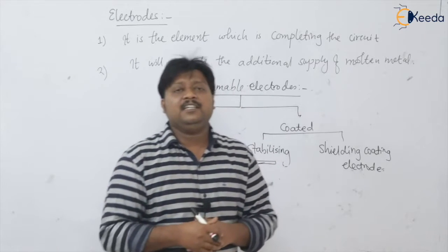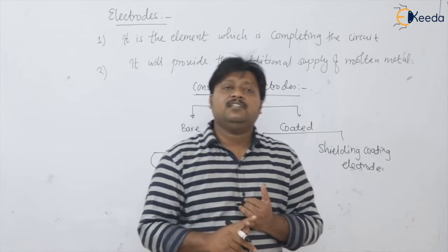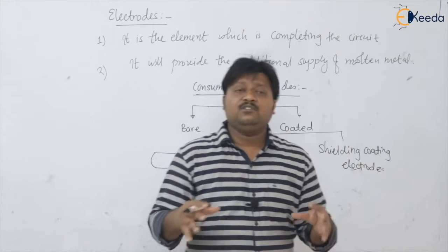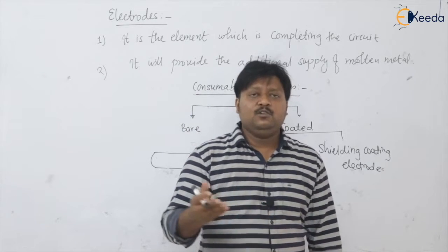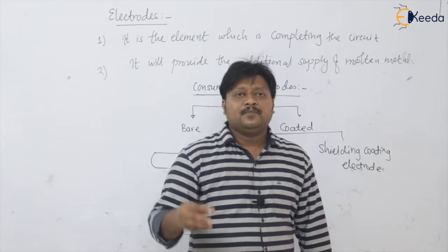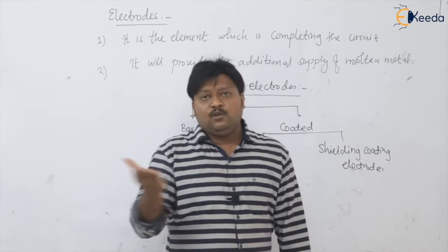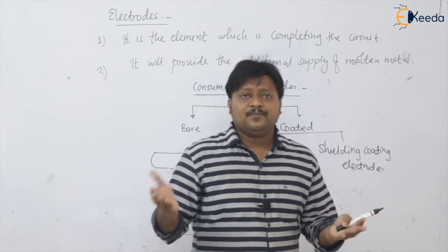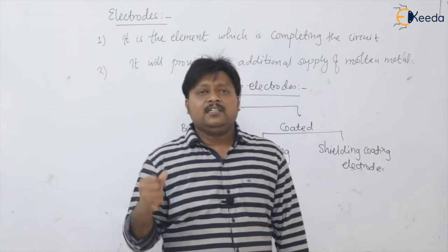So first thing, definitely we are going to get the deoxidization of the melt. That is the very first advantage we are getting. Then if any harmful gases are present around the weld zone, they can get absorbed, that is the second thing. Third thing, we know some portion of fluxes melt and react or combine with the impurities in the weld and float over the weld pool and act as a slag. This is nothing but the slag, which will again safeguard our weld from the atmospheric contamination.